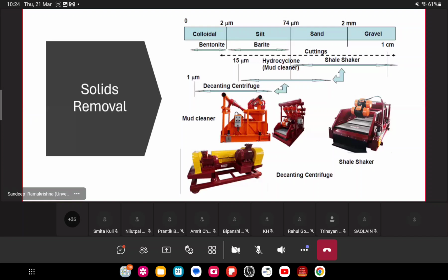Every pipe, you won't believe it, even though there are sophisticated equipment these days to move stuff around, you would see that people are physically measuring pipes, using a tape measure, measuring length of the pipe, numbering the pipes, knowing the ID, that's inner diameter, OD, outer diameter. So using the slide calipers.